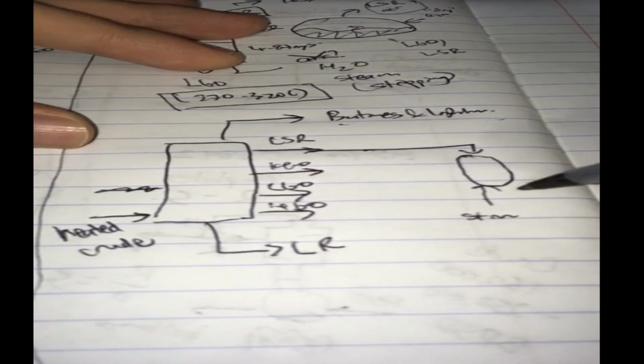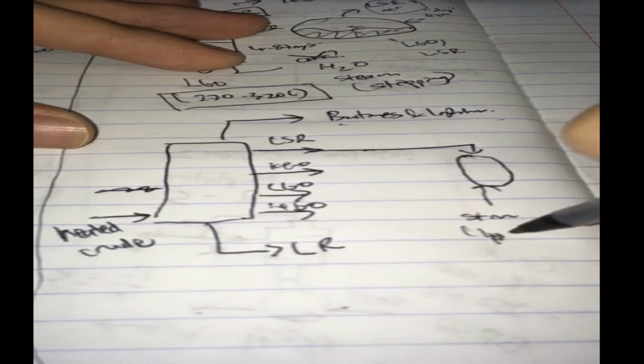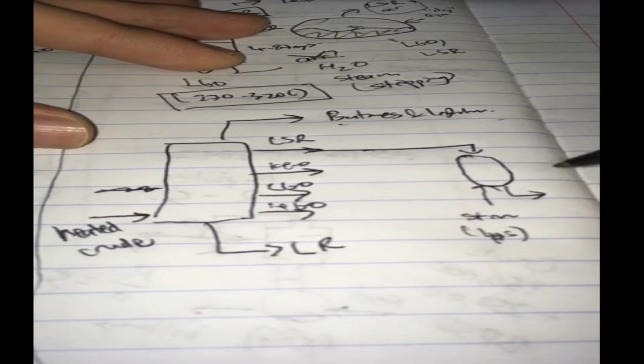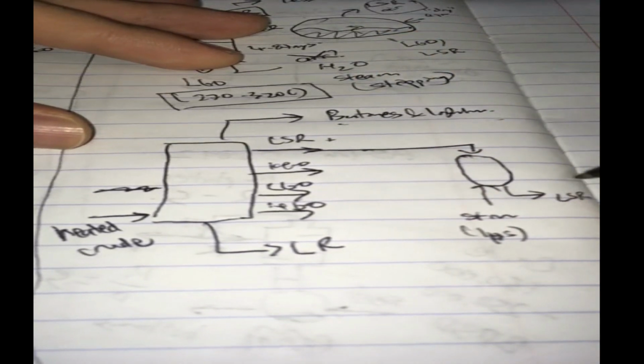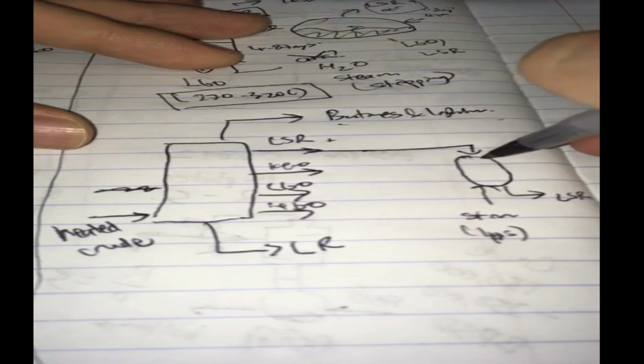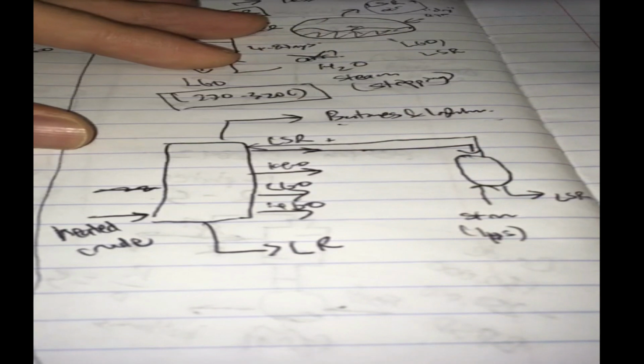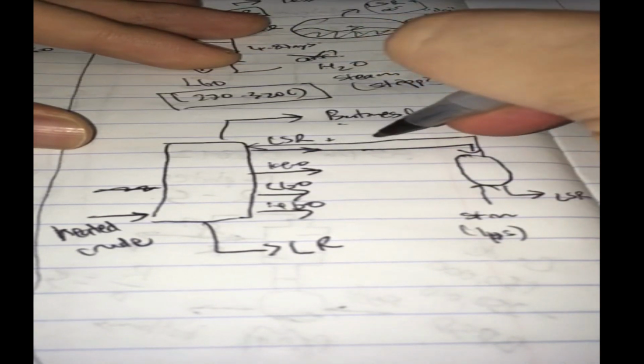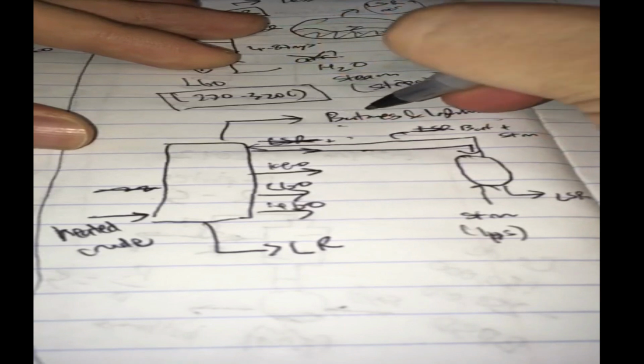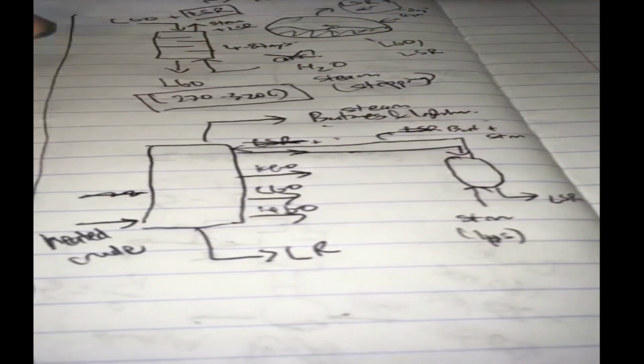So we have steam here, or low pressure steam, they call it LPS. So light straight runs plus other stuff. So the stripping will help to get rid of the butanes and lighter stuff and pumping back as the gas form into the tower. Alright, so this is light straight run, this top stream, or rather butane plus steam. Butanes and lighter plus steam. So the top column is going to have steam.